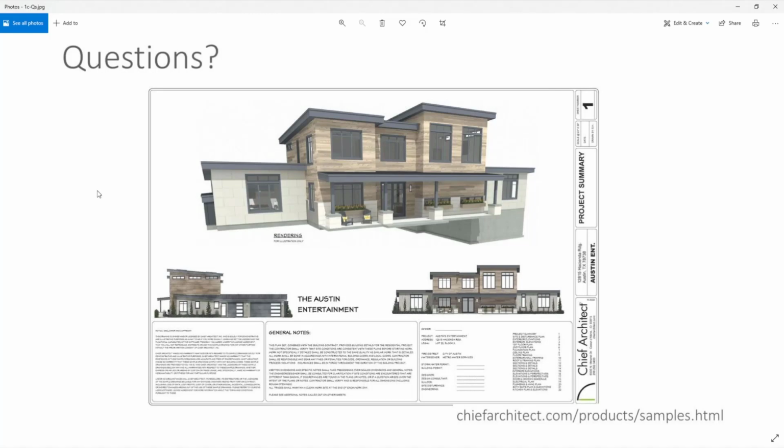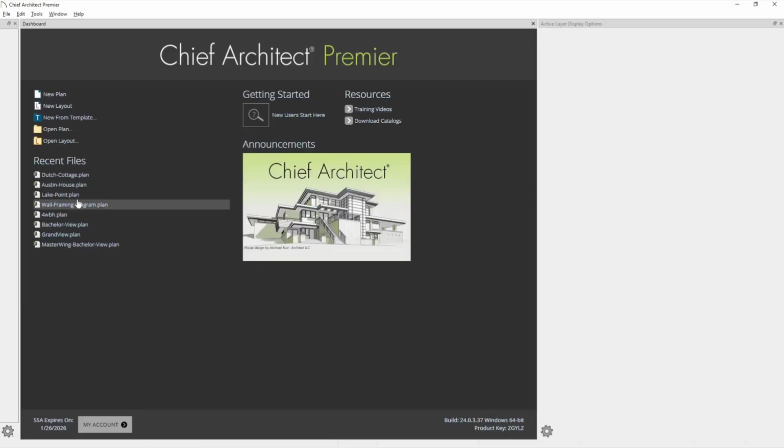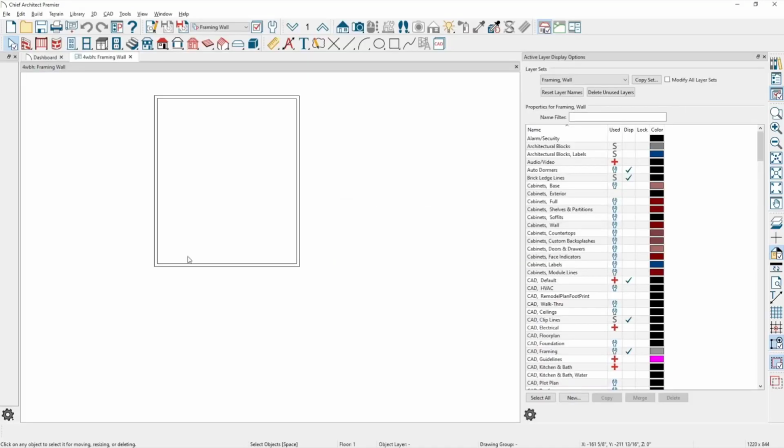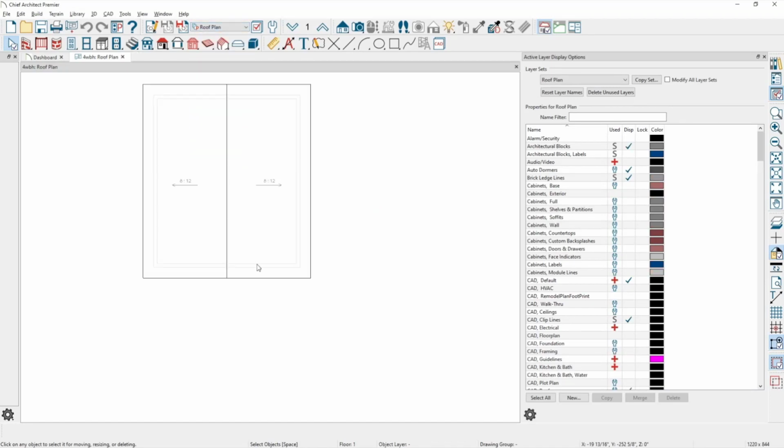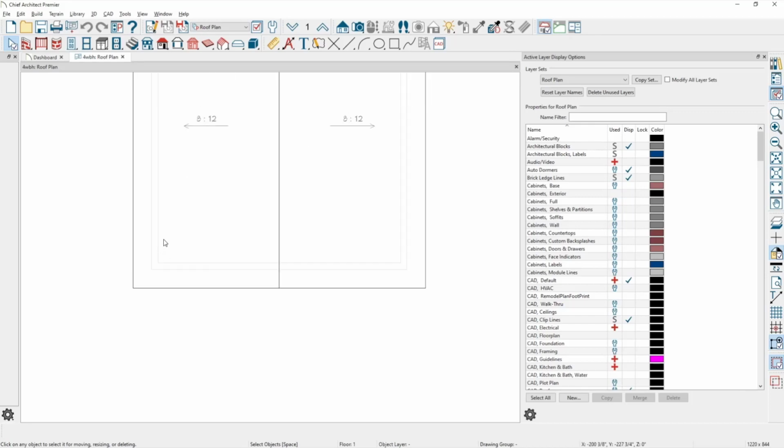What I found is that unless I very carefully calculate the height of that highest wall, it will insert a little attic wall that's about 6 inches tall. And I also have a problem with interior walls meeting up with that ceiling when I do an offset gable. Sometimes they'll stick right through the roof. Sometimes they'll fall short. I can't seem to get them to automatically fit the new roof. Right.